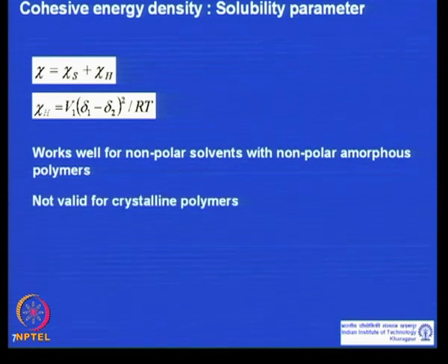It is not valid for crystalline polymers because this approach talks about liquid solvent and liquid polymer, meaning amorphous polymer. So, if you want to dissolve a crystalline polymer, then you also have to include the contribution of the enthalpy of crystallization. In this case, that enthalpy of crystallization is not taken into account. That is why this approach is not valid for crystalline polymers; it is valid only for amorphous polymers.